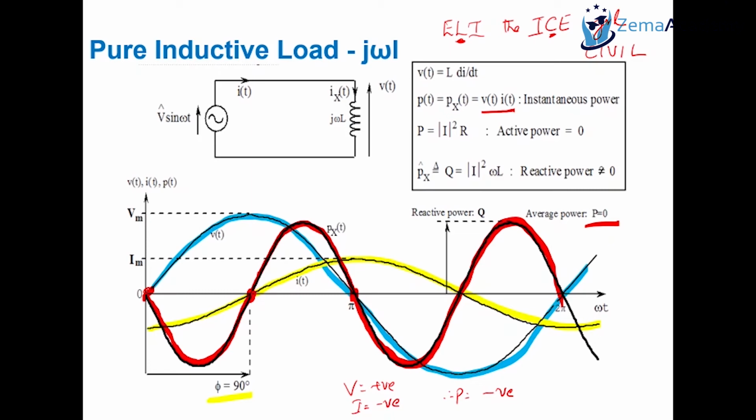Yeah, and for the next 90-degree interval, where the power is positive, the power is transferred from the source to the load. And then it repeats itself. And because at regular intervals you have a set amount of power that's being exchanged between the transformer and your house, the net power, average power, is zero. Okay? I'll come back to it again.